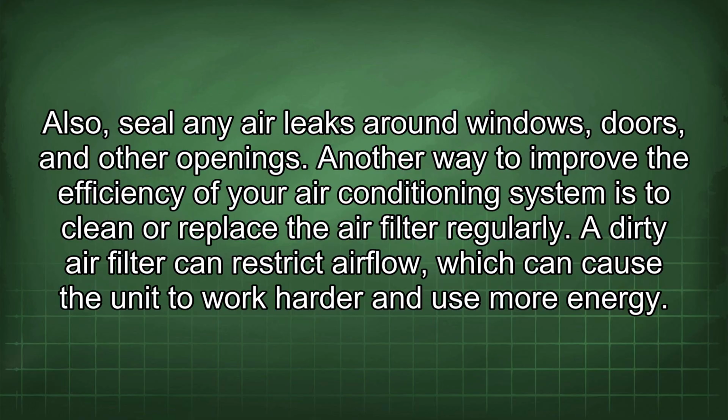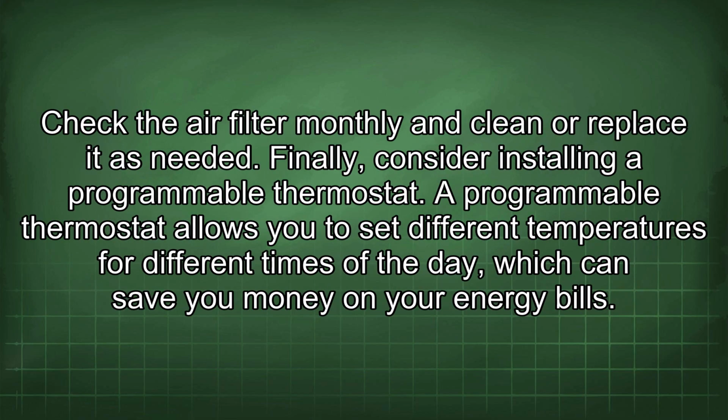Another way to improve the efficiency of your air conditioning system is to clean or replace the air filter regularly. A dirty air filter can restrict airflow, which can cause the unit to work harder and use more energy. Check the air filter monthly and clean or replace it as needed.